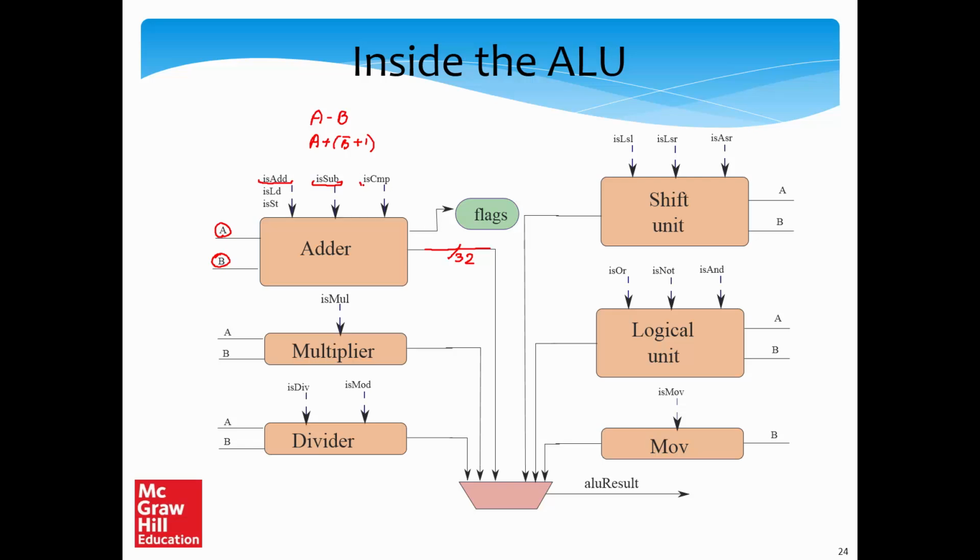Then, this subtraction and comparison is the same thing, in the sense that when we are comparing A and B, what we do is subtract B from A, and based on the sign of the result we set the flags. So isCompare is the same as isSub, it's just that it will set the flags.